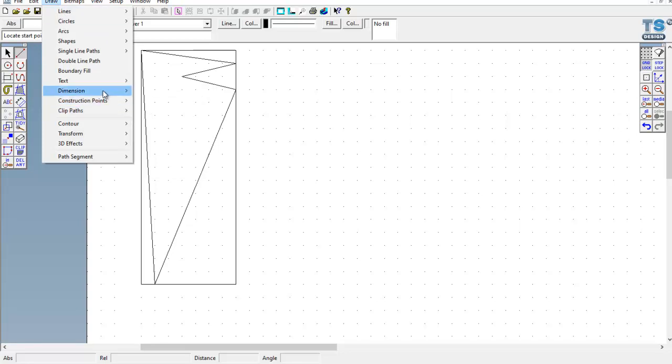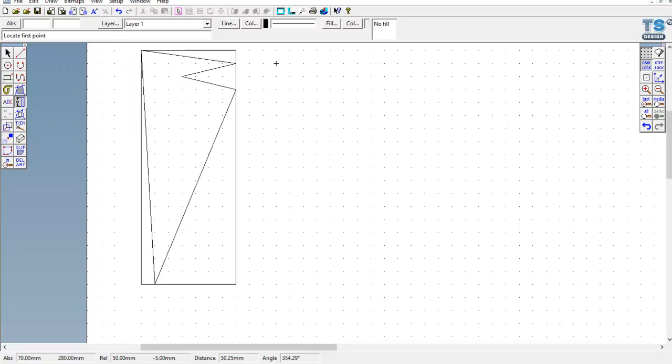and if I do the vertical ones first of all, what I can do is click onto the top of there, onto the bottom of there, and take that across, move it so it's inside, which will tell me it's 90. I can work out this space down here and that space there, which should tell me that it's actually 5mm. I can do from this top bit down to the bottom part, which should tell me it's 10mm, and then I can do from this part down to this part, which of course will be 15mm.